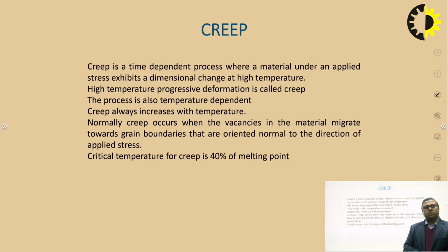Creep is also known as a time dependent phenomenon because as time progresses, we see some deformation in a material whenever a constant load has been applied. This constant load at constant high temperature causes the material to deform, and this phenomenon is known as creep.